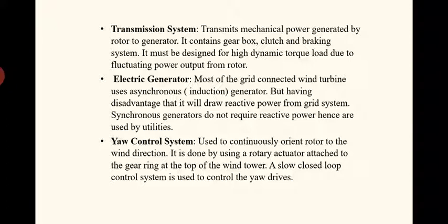Okay. Now coming to the last component, that is the electric generator. Most of the grid, as you already know, the function is to produce the electricity. Inside we'll have the magnets as well as the coils. Once the coil cuts the magnetic flux, the electricity is produced. Most of the grid connected wind turbines use asynchronous induction generators, but having the disadvantage that it will draw reactive power